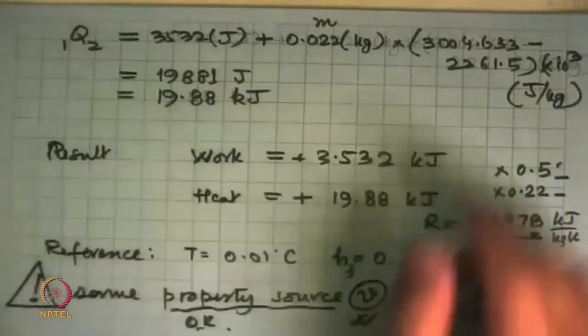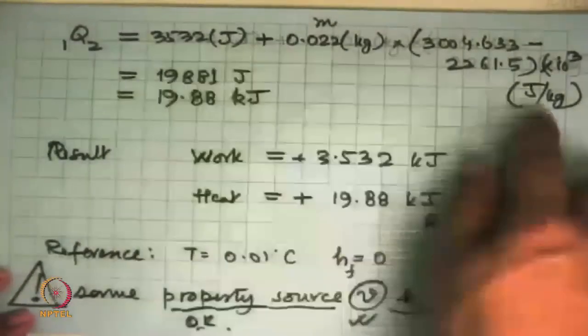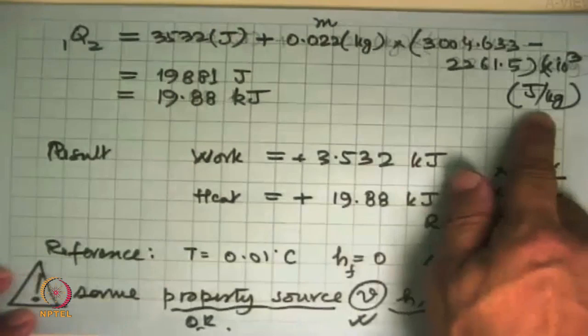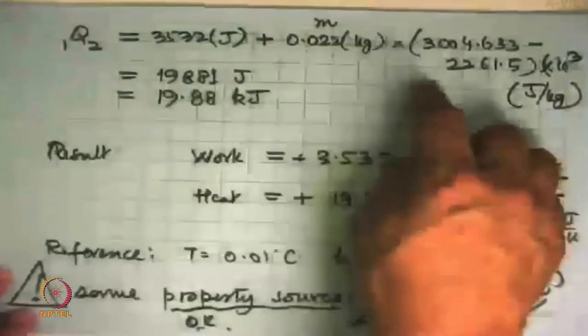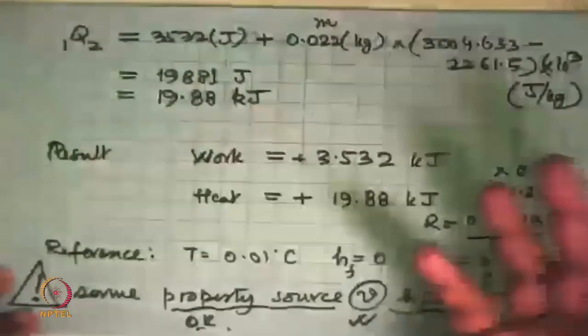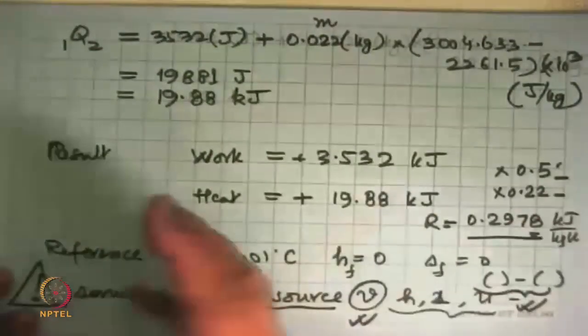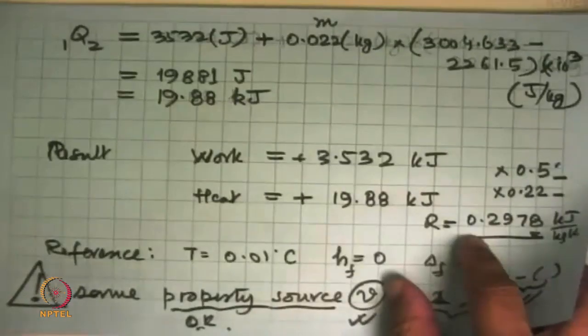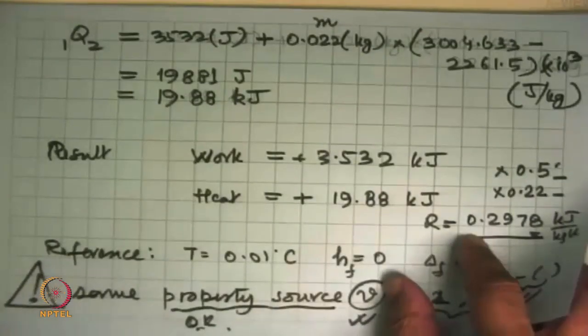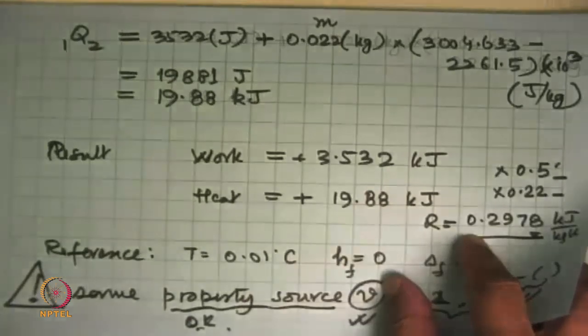Please also make sure that you write the units at every step. That way you will avoid a common problem: quite a few people, when doing a PV type of calculation, take pressure in bar where it should have been taken in Pascal, and the complete answer goes haywire. The process is okay, you are at least 90% correct, the last number would be only 10%.